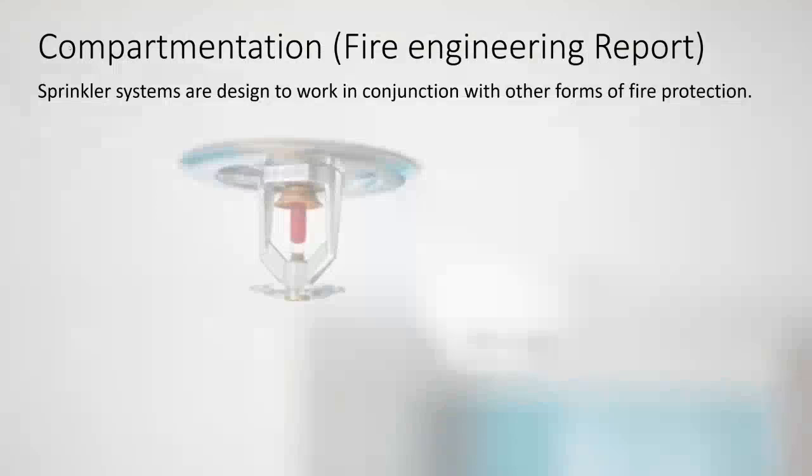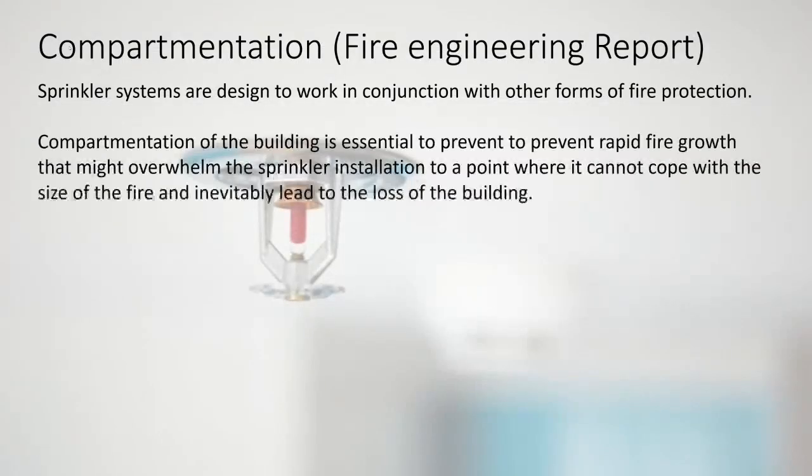So the compartmentation is a very important part of sprinkler design. Sprinklers are designed to work in conjunction with other forms of fire protection. Compartmentation of the building is essential to prevent rapid fire growth that might overwhelm the sprinkler installation to a point where it cannot cope.